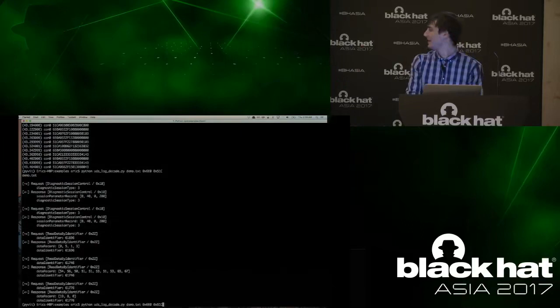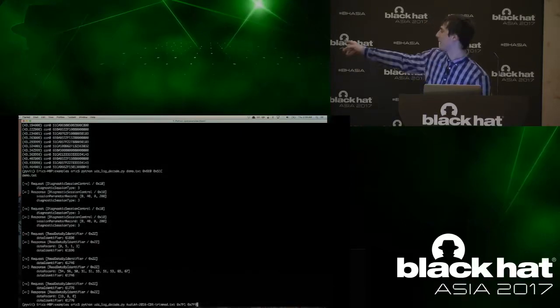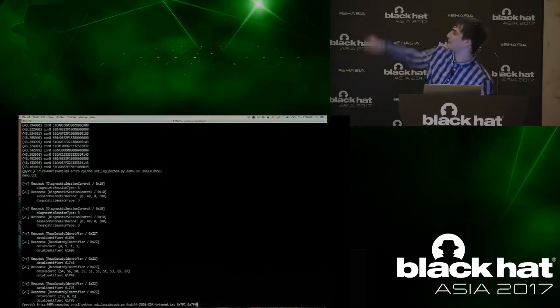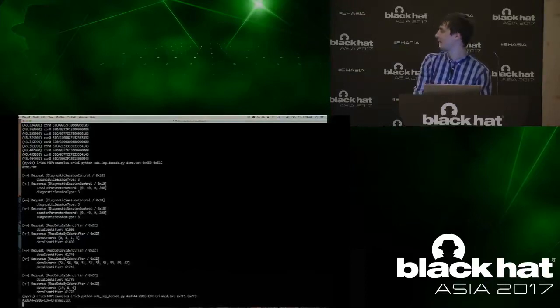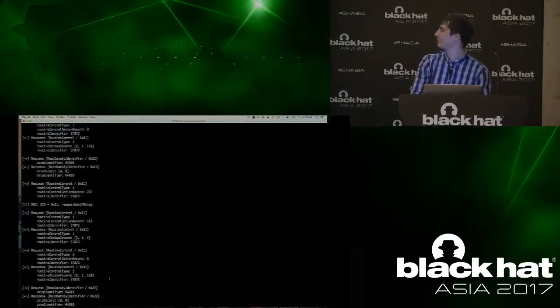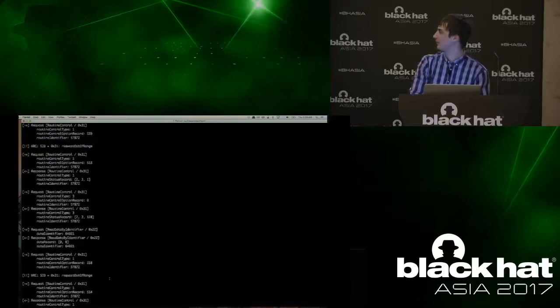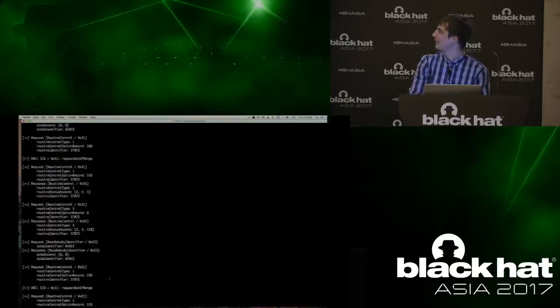But just so it wasn't a contrived demo, we can also do a different car. It's probably a little hard to see, but the last two parameters there, so for the last one it was 6E0, and before that was 51C. That's the request and response IDs. So we can run this. This is from an Audi A4 crash data recorder, and this one's actually pretty short for a crash data recorder session. And we can scroll back.